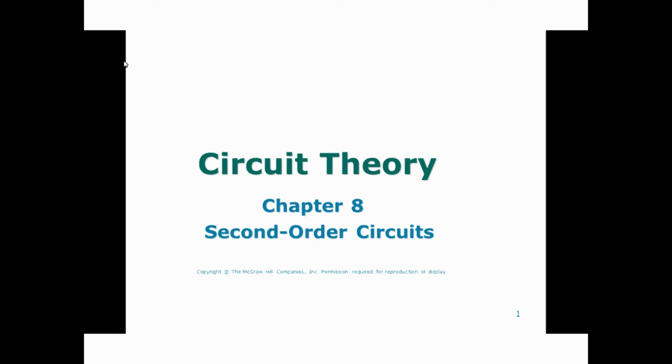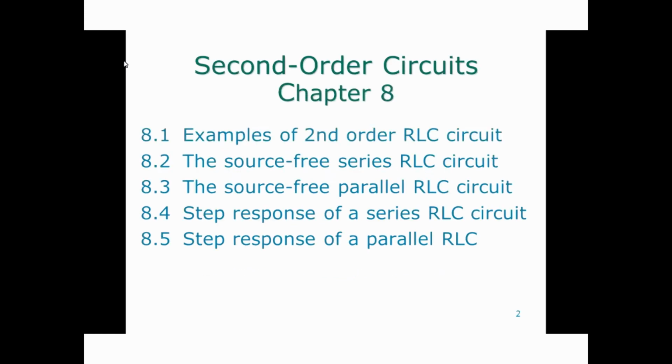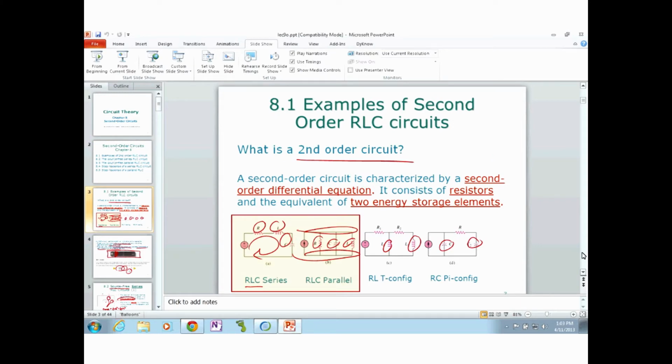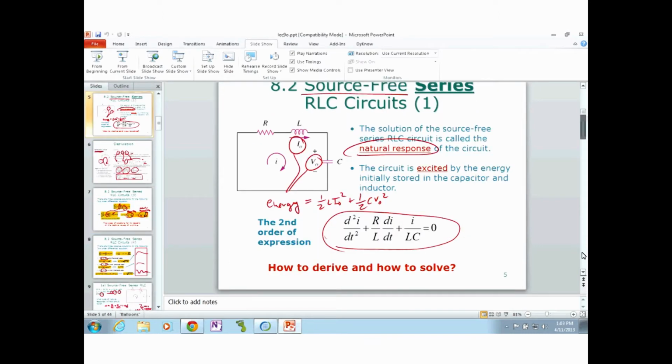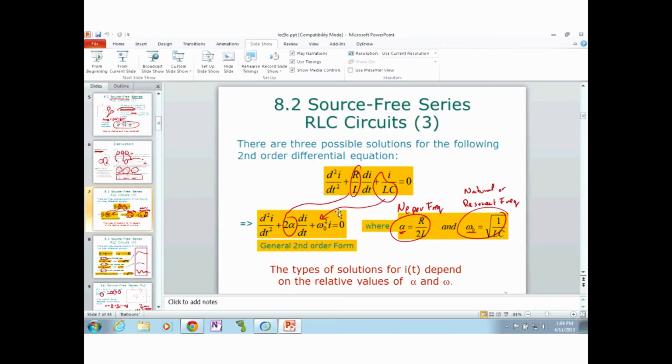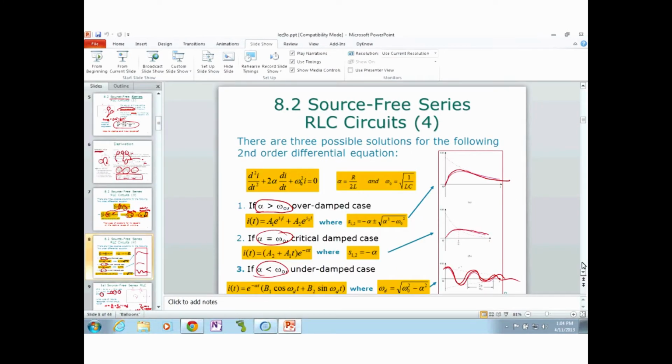All right, let's focus now on second-order circuits. You might have to jump around a little more before coming to class because these take a lot of focus. So we looked at the process of solving second-order circuits. The first step we found is that second-order circuits form a second-order differential equation, and the steps in solving that are, basically, you propose that the solution is a sum of two exponentials with different decay rates, S1 and S2.